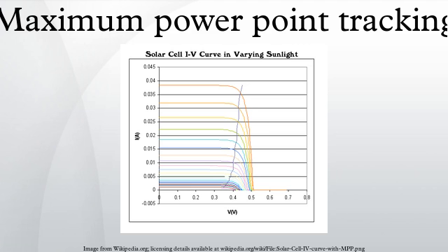MPPT placement. Traditional solar inverters perform MPPT for an entire array as a whole. In such systems the same current, dictated by the inverter, flows through all panels in the string. Because different panels have different IV curves and different MPPs, this architecture means some panels will be performing below their MPP, resulting in the loss of energy. Some companies are now placing peak power point converters into individual panels, allowing each to operate at peak efficiency despite uneven shading, soiling or electrical mismatch.